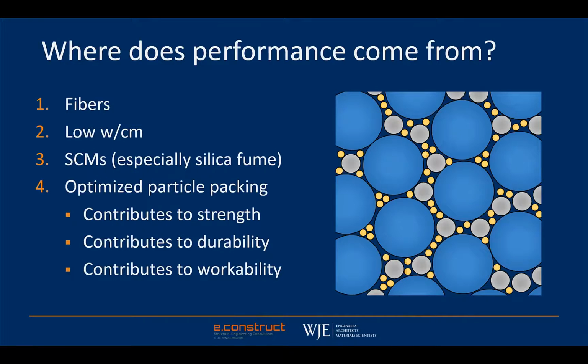But it also contributes, and this may be a little bit unexpected, to the workability of the material, because there's just less space within the material where water can exist, and that's what provides the fluidity to the material. So for all of the mix development efforts, this optimized particle packing was front and center in what we were doing.